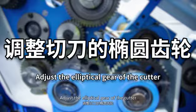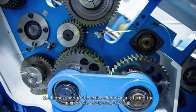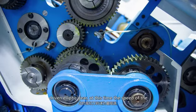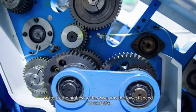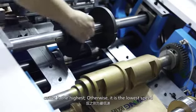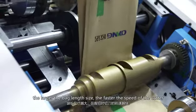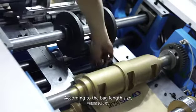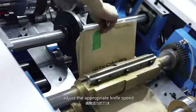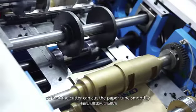Adjust the elliptical gear of the cutter. The highest part of the active elliptic gear is facing the driven elliptic gear. At this time, the speed of the cutter is the highest. Otherwise, it is the lowest speed. The larger the back length size, the faster the speed of the cutter. When cutting, the reverse is slower according to the back length size. Adjust the appropriate knife speed so that the cutter can cut the paper tube smoothly.